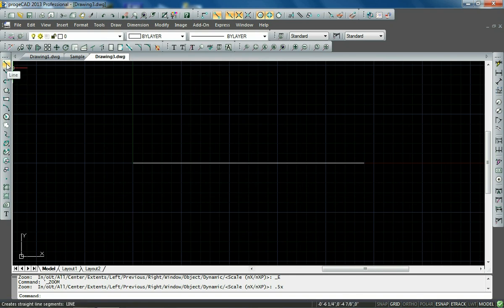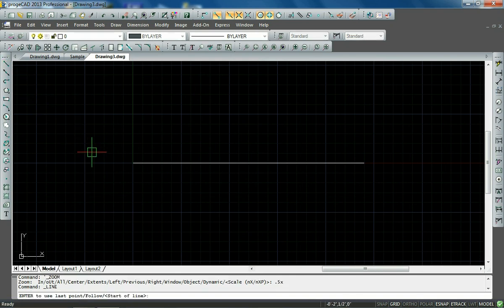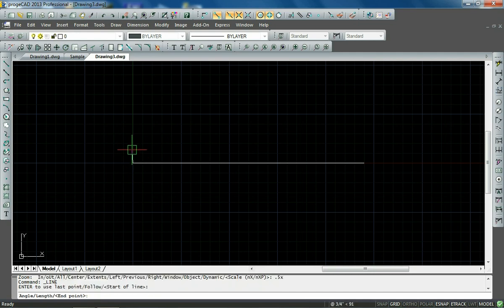Start a second line using this line as a reference. Select Line. Then use your snap to capture the left side of the line you just drew. If your snaps are not on, see the Help section and turn on Endpoint, Midpoint, Quadrant, Center, and Intersection as usual snap points. It's very handy.